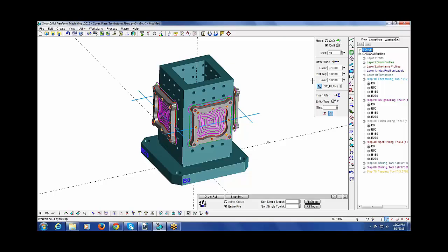You can associate those tools and steps with materials and machines. You can store groups of tools or groups of steps with their assignment numbers for a variety of purposes. It could be for templates, it could be for tool catalogs, it could be for machine setups, it could be for groups of steps to machine features. We've shown you that you can filter when selecting those items based on material and machine and group and type.